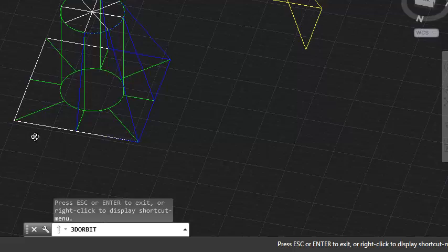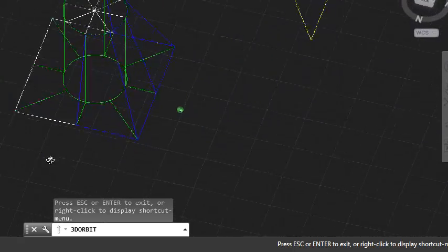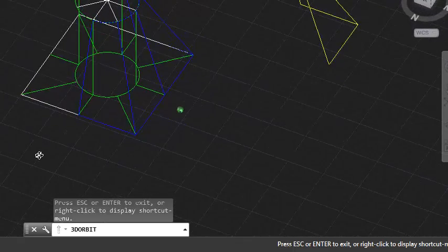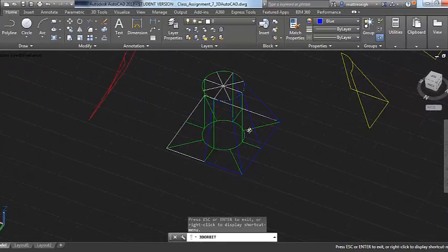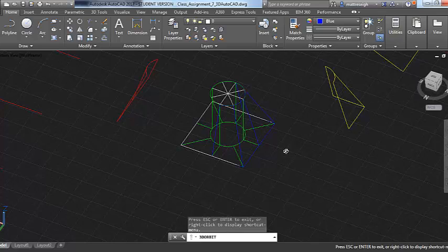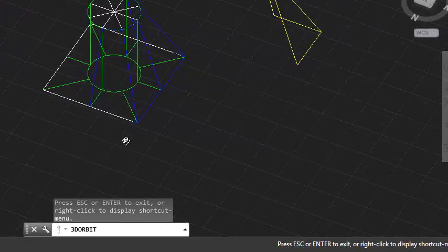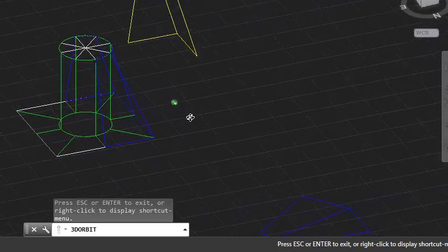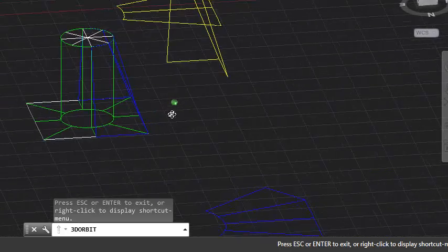But I feel like it's a little bit of a pain on your press brake operator. And I totally prefer a couple more weld seams and something easy to handle in the press brake. And these are just a few of the ways that these kind of transitions can be done. There's still drafters that would do these even differently. This is just a real standard way that's been done for a lot of time. And if you look online for squared around transitions, you'll see a lot of these very similar shapes that we're doing here, similar patterning that we're doing.